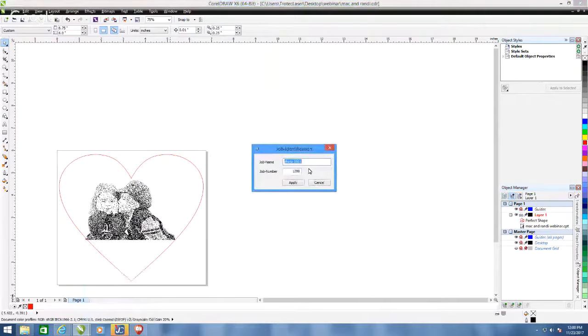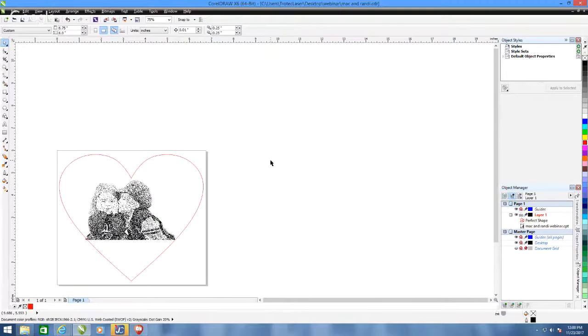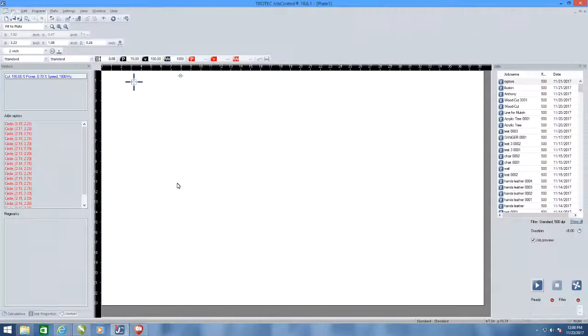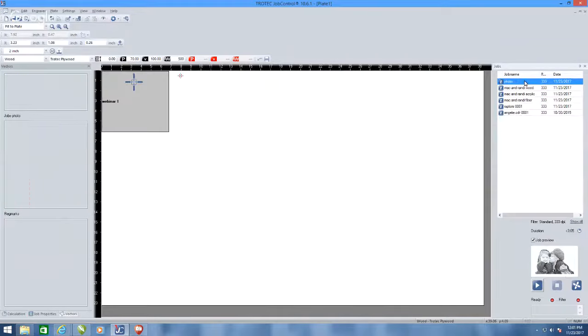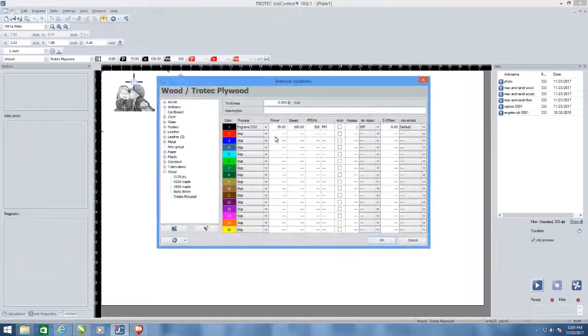Then I'm going to give it a name here. Again, we're going to call it webinar. I'm going to go into the job control software here. Again, you notice here, I'm looking at 500 DPI. I've sent over something that's 333. Just double click on that image. So there's my image right there. And I want to do a cutout on the actual material under power and speed. Actually, probably 1.5 is 120 watt. Turn my air assist on.